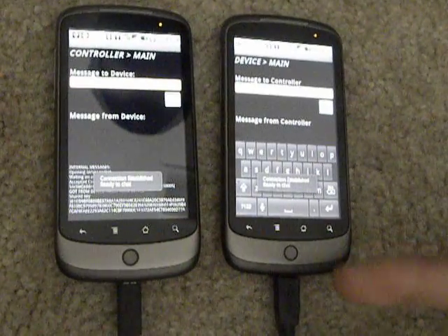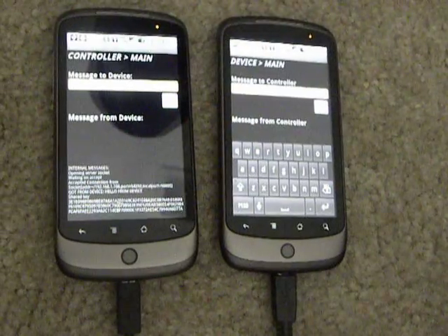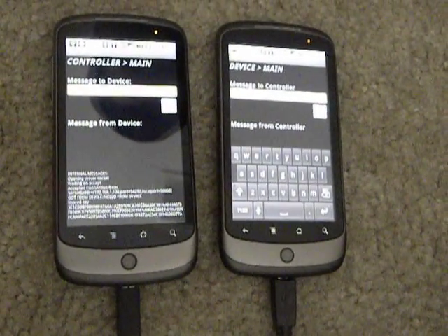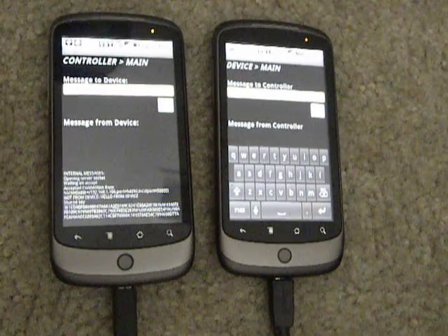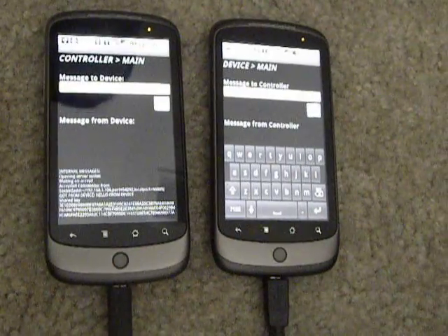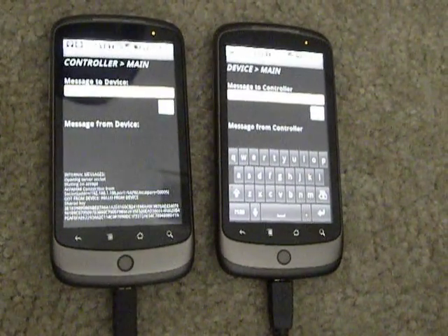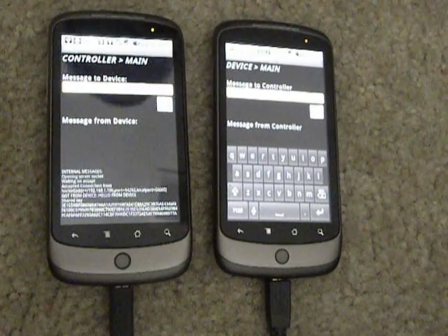We have just seen a toast notification saying connection established, ready to chat. What has happened in the background is the SSP protocol is completed, with 4 phases of the protocol, and a link key is established between the two devices. Both the devices also have self-signed certificates. Those certificates are exchanged using that particular link key.